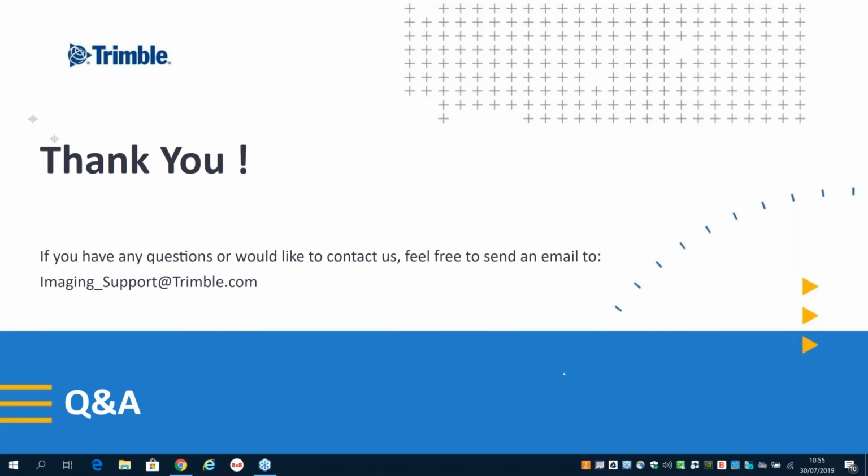Yeah. So we always say that the MX9s, or the mobile mapping systems we produce, are mainly for land usage, so not for marine. But it doesn't mean that it could not work for marine. It's just that maybe we don't know how it will behave in marine, because basically what we use inside our systems is a navigation system called LV from Applanix. And we don't use the MV, which stands for marine vehicles. So we use the LV for land vehicles. The problem with marine applications is that there is a motion called the heave motion coming from the waves. And the IMUs used in land vehicles are not dealing well with the heave motion. So they are not adjusted well to take care of the heave motion and compensate for that.